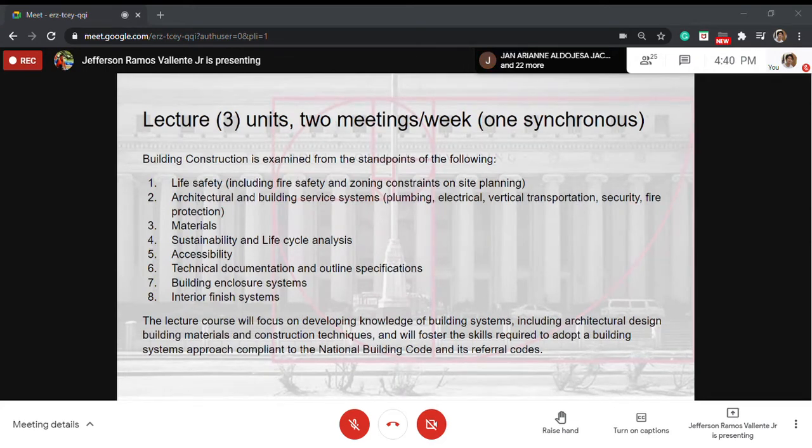Third, we'll discuss the different material types that you need for construction, from architectural requirements, say the tiles that you need, the paint that you need, or even the lighting. For construction, you also need to consider structural requirements, say how strong the concrete will be, what type of cement you will be using, or even the grading of your coarse and fine aggregates.